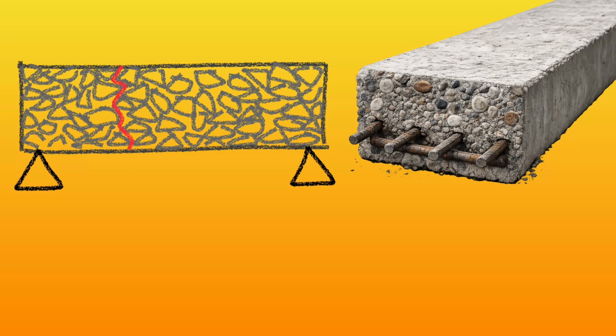So that vertical red line that you saw before won't actually be vertical, because it's got to follow the line of the aggregate, and it's that aggregate interlock that gives us a good shear capacity, further enhanced by the cementitious bond. Unfortunately, on big heavy structures where you've got big loads, there's only so much that the concrete will do. It's not got an amazing shear capacity, but what has is steel reinforcement. So by placing some steel reinforcement in the tension zone, you can dramatically increase the capacity.